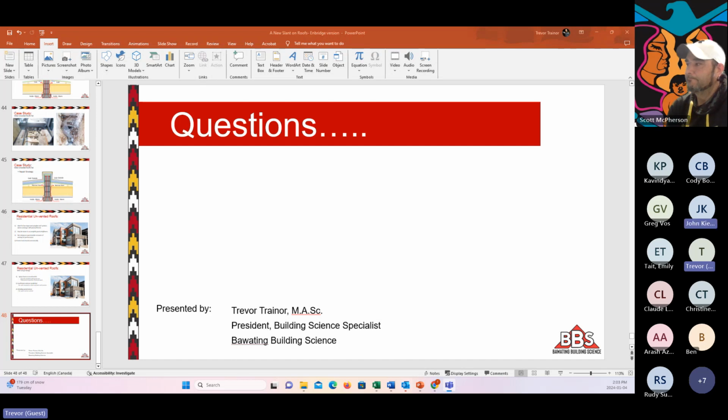Okay. Yeah. Scott, is that a big issue for you guys? No, it was just a thought that crossed my mind towards the end of the presentation. Because I know we get moisture in the walls due to vapor barrier and stuff like that. I was just thinking, okay, ceiling, attic, and air movement. Because of the air movement later on, if it's a blown-in batt, the insulation moving and then the constant heating and cooling of that poly, just eventual breakdown. That was the thought that was crossing my mind.